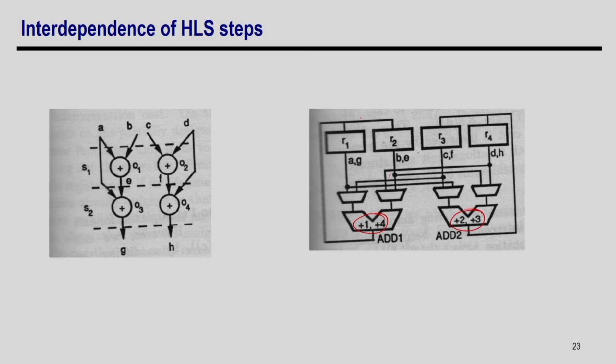So, you do not need the input muxes, right. So, you still need the muxes at the input of the FUs. So, how many muxes are needed? 4 muxes and 4 control signals. So, your control reduced from 6 to 4, right. So, some improvement is happening. So, you can understand that same schedule, but different allocation and binding cost different interconnection cost.